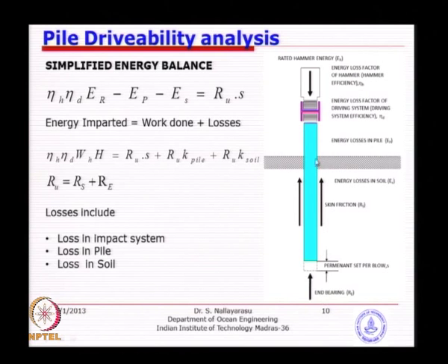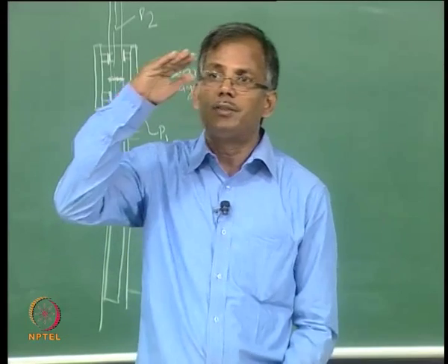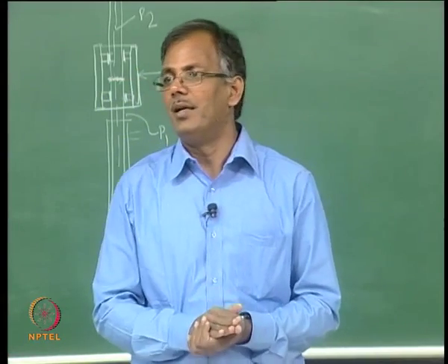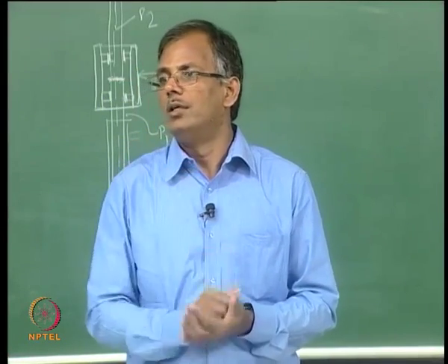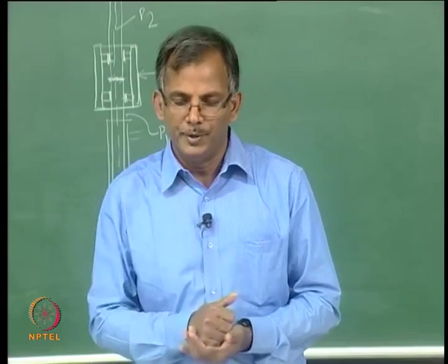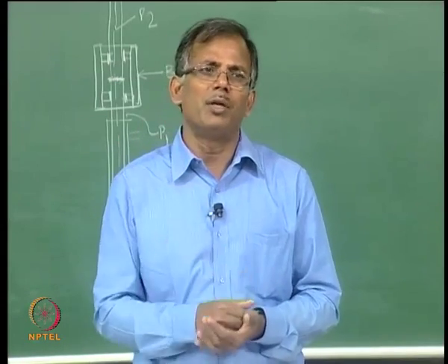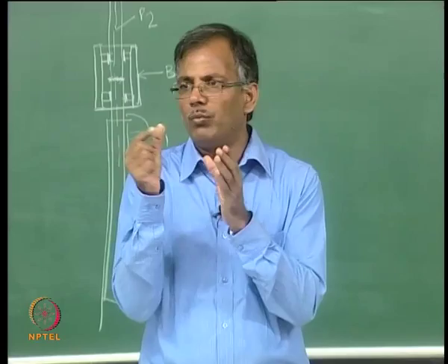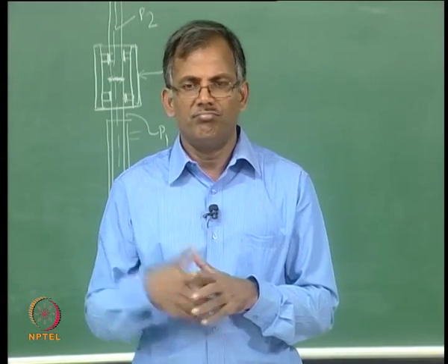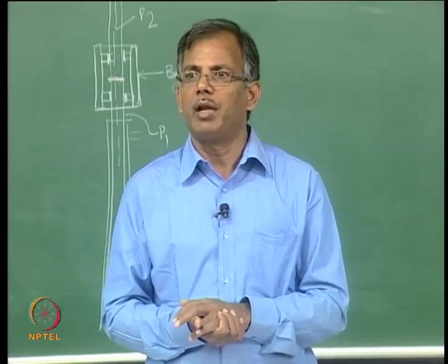Some energy is also lost in the pile itself, because the pile will get compression, isn't it? Because you apply an axial load to a steel material, for sure axial displacement will happen, strain will happen. So some energy is lost, but that will be very small because the pile has such a large diameter and wall thickness, and the compression will be too small.